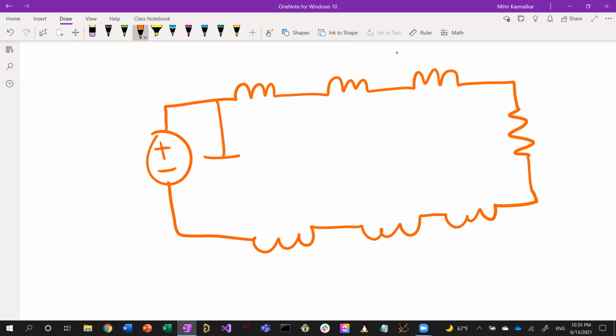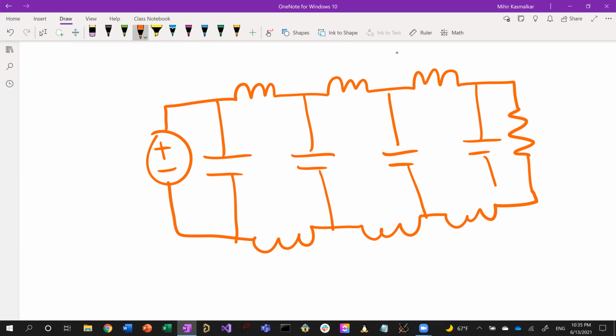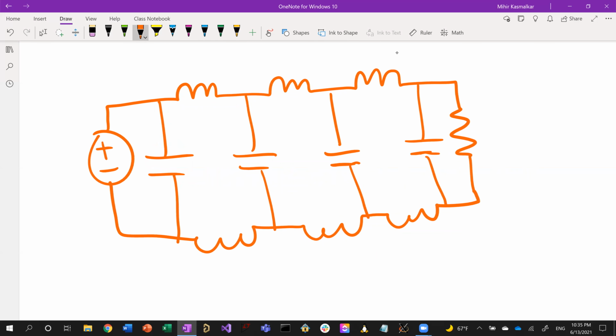Okay, so you have your transmission line, and it's terminated in a resistor. This resistor has a specific resistance, which is Z0. Remember, the transmission line has a characteristic impedance Z0. It acts as a resistor with a value of Z0. And so this resistor that we've terminated with has a value of Z0.